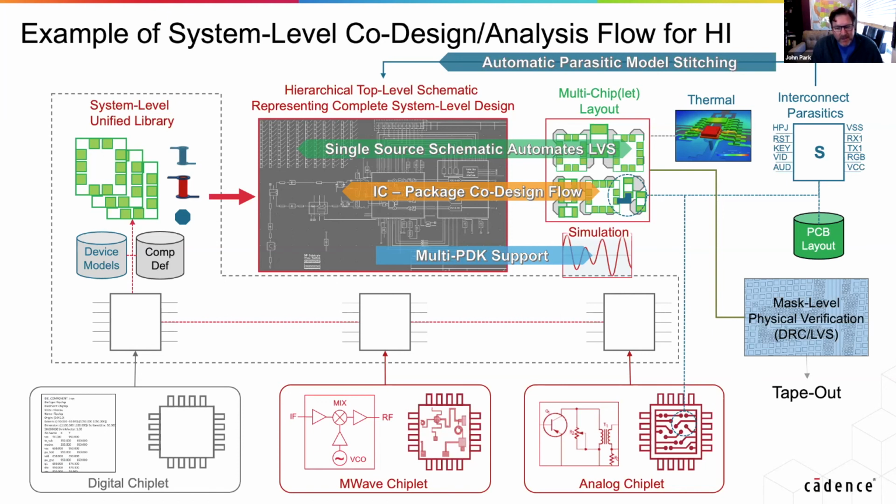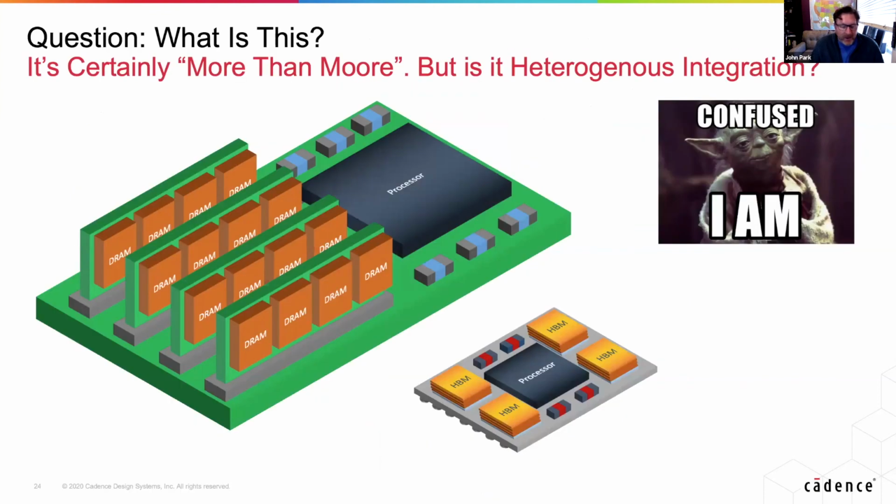So this doesn't show all the steps within the design flow. I didn't talk about timing here. That's another topic. If you talk about STA, because you're an ASIC designer, SoC designer, that goes away. You're dealing with passive fabrics here. So silicon interposers and laminate substrates, there are no device layers. So I can't insert a buffer or make a buffer stronger to meet timing. All I can do is wiggle lines around. So timing becomes more about constraint driven routing to match signals and those types of things as you move forward. So I'm going to wrap up here real quickly with a